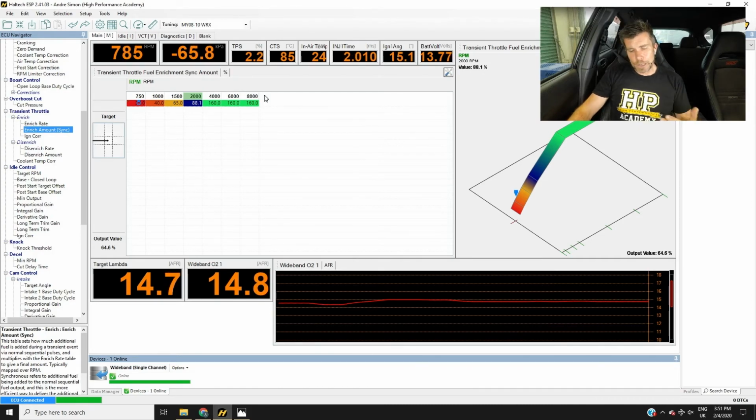Now, this is a little bit complex and there's a few things to understand here, but essentially what it's explained is that this is a pseudo VE number. So this is looking at an assumed volumetric efficiency number from the engine. So understandably, as our engine RPM increases, our volumetric efficiency also increases within reason. It's not going to increase forever. So that's why we start seeing those numbers actually increase with RPM rather than decrease like we'd traditionally expect.